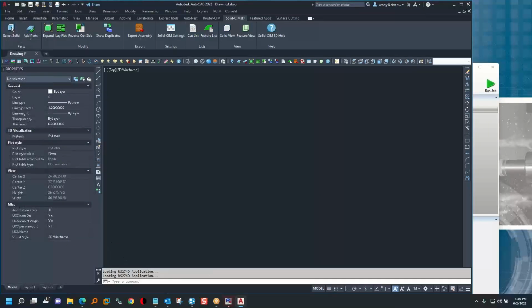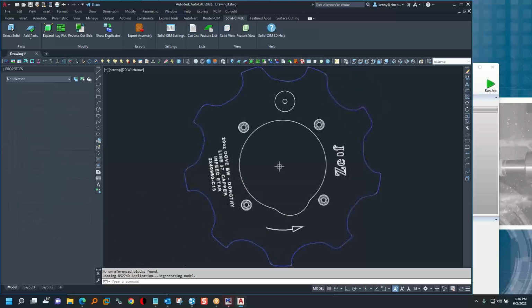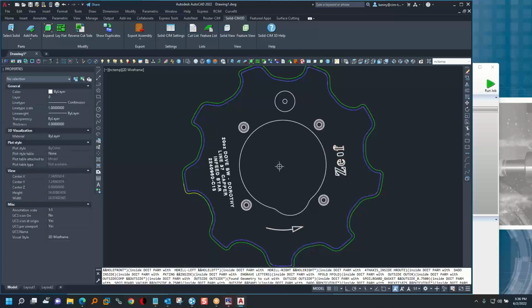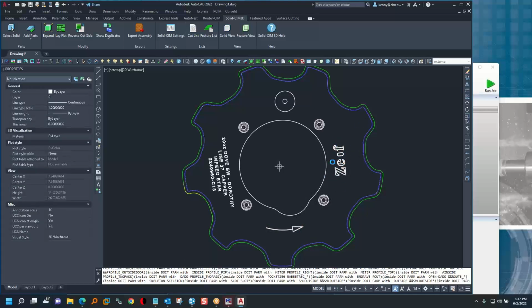And because there was a counterbore on one side, countersink on the other side, I have it turned on for 2-sided nesting. So I have this embossing geometry all on a layer that gets engraved. I have like a little V-bit set up to go at whatever depth you drew it at.